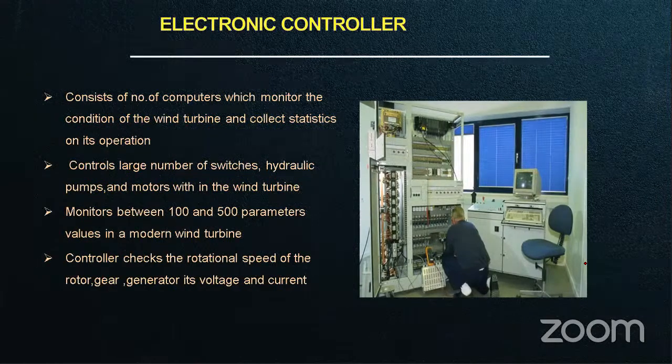In case of extreme external conditions, like all of a sudden you have a storm, the turbine should not keep generating power, because in extreme conditions we do not know how much turbulence there is going to be, and the direction will also suddenly change. At that time we have to stop the turbine, and also limit the turbine power at a certain meter per second. Generally, at 25 meters per second it has to stop.